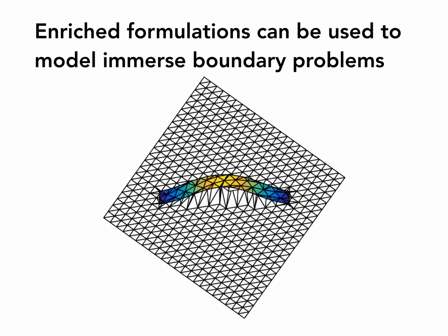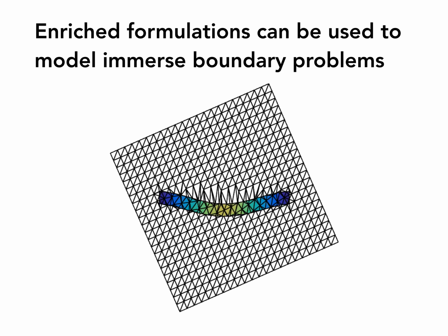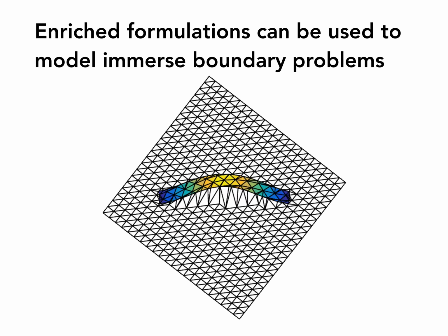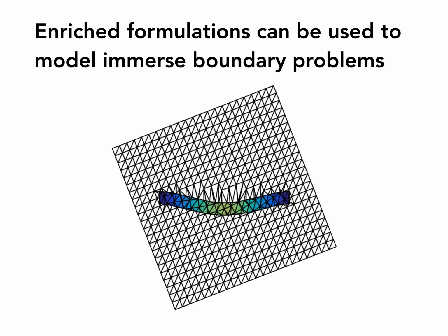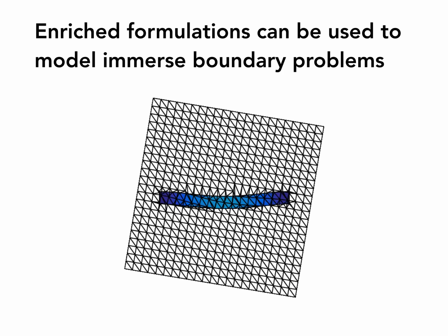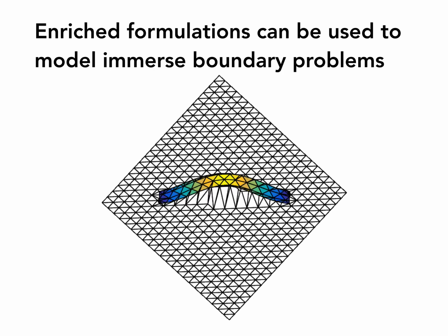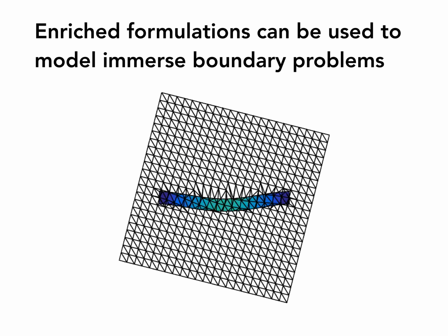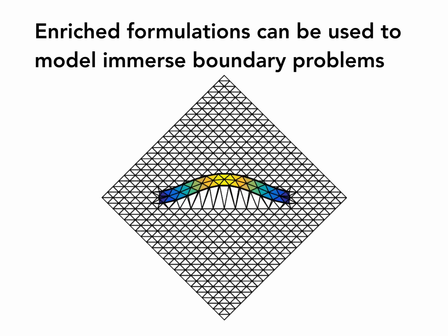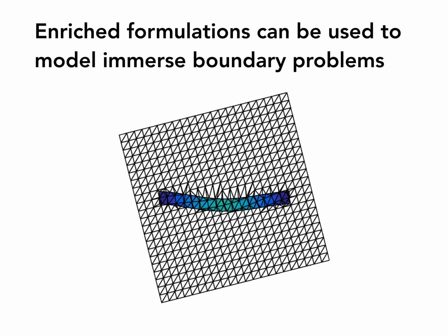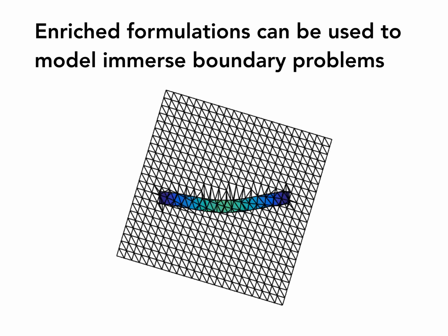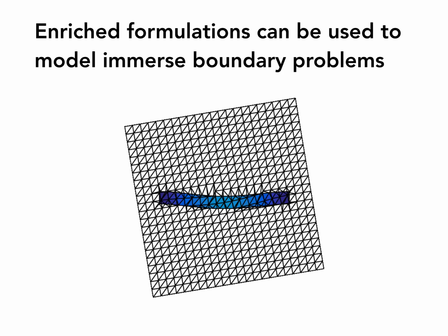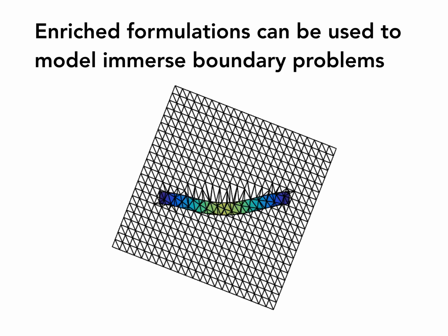The last one is immersed problems. So imagine now you have an object, whatever it is, and you want to analyze that object by just immersing it into a very simple structured mesh. And this is what you see here. This is just the first vibration mode from a beam, but I immersed that beam in a mesh. And to show you that it's truly mesh independent, every frame of that vibration mode has been obtained by rotating that mesh slightly by 3 degrees. So it's very impressive, the things that we can do with Enriched FEM.